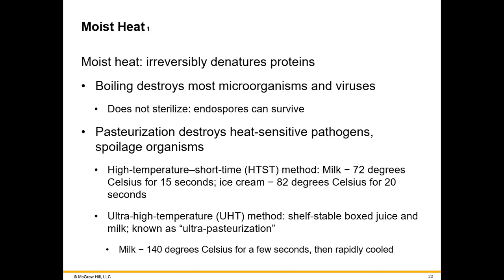Okay. So in the old days, they used to use lower temperatures, of 56 to 65 degrees Celsius for 20 minutes or 15 minutes, sometimes less. But commercially, that is not effective. Today, they use the so-called high temperature short time method, whereby they raise the temperature up to 72 degrees Celsius. And you only need to expose the milk to that temperature for only about 15 seconds